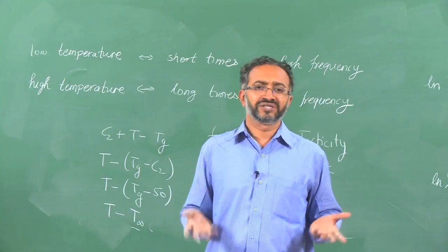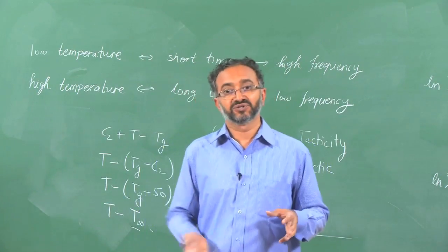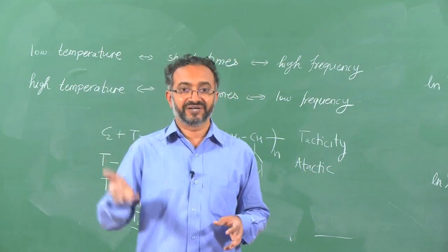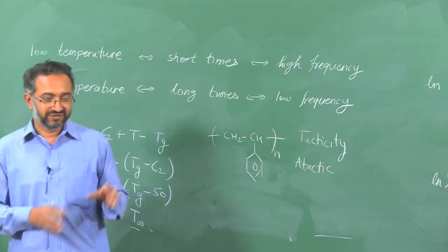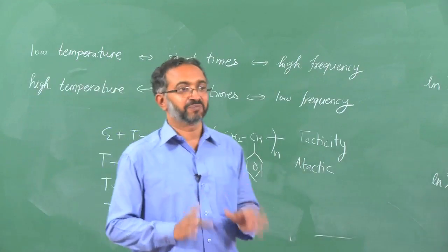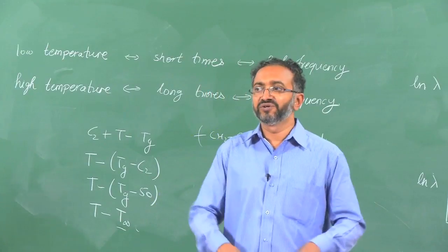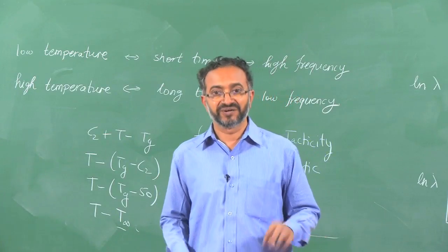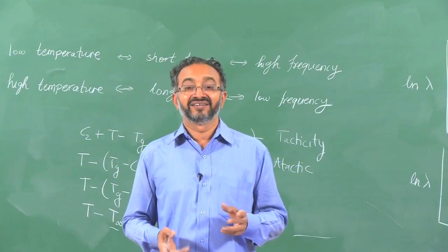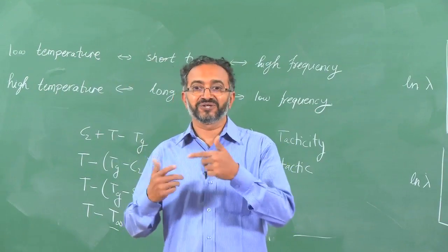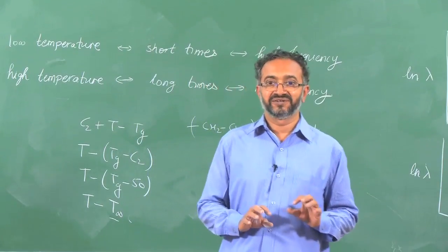So, at 300 no other thermal event should be there, but if there are chain scission reactions, those are exothermic, so you will get heat of reaction. So, things like that. We always have to supplement rheological analysis with other things, but this will give you a clue. If time temperature superposition is working, it still does not mean that processes are not happening. Sometimes the cancellation of two processes can give you some result, right. So, that of course we always have to worry about.